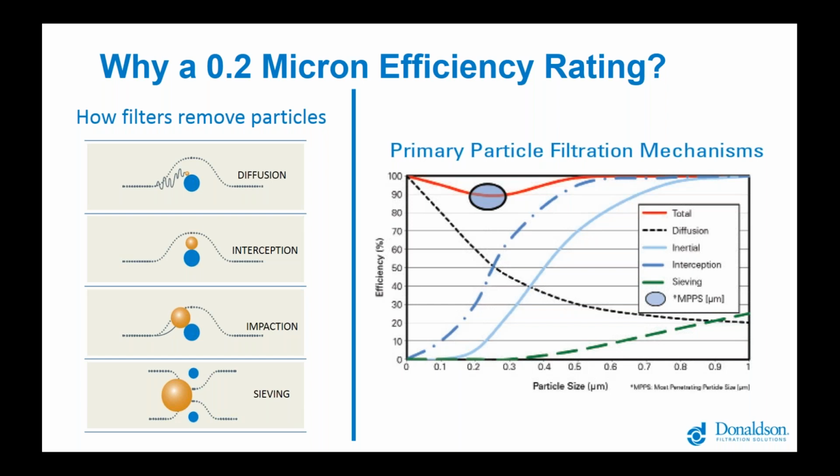So don't go out and assume that if you find, for example, a 0.1 or 0.01 micron rated filter, that it's actually going to be effective at this 0.2 micron size. The industry in general has kind of polluted the topic and made it difficult to understand, since it's typically counterintuitive that very small particles can actually be easier to capture than some larger ones, but it's true.